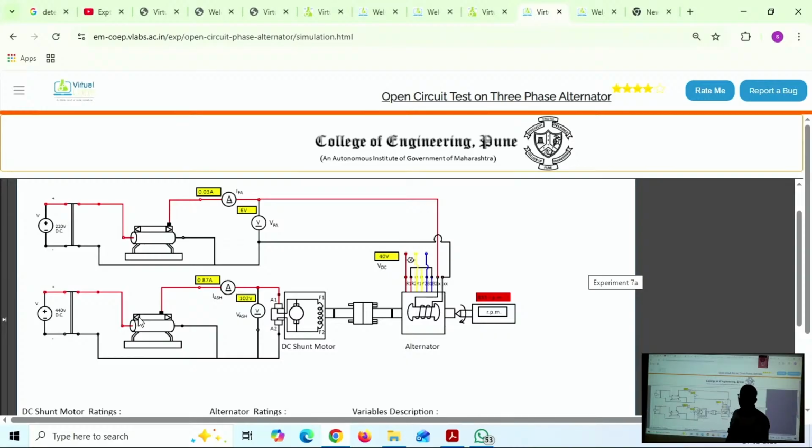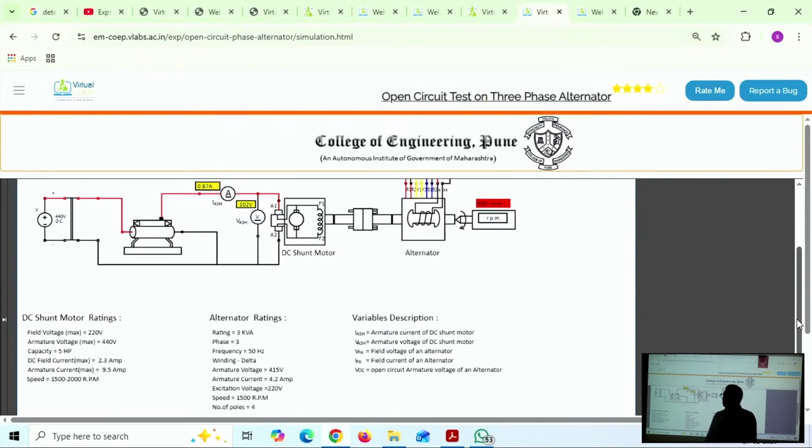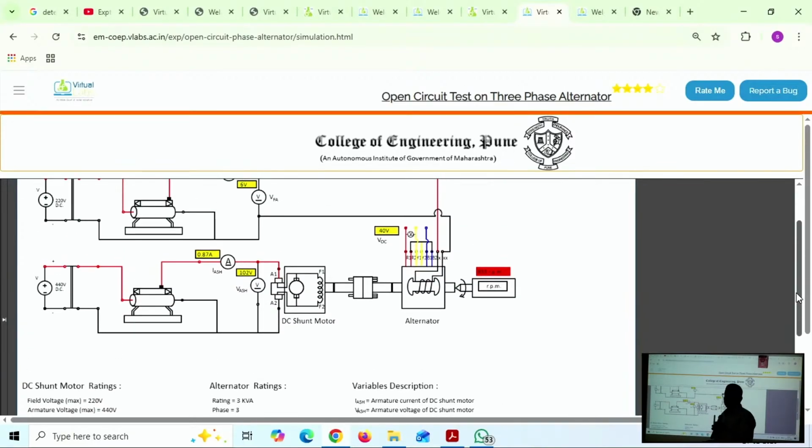So what should be employed? Speed control can happen in two ways: below the rated speed or above the rated speed. What control should we adopt here? If it is below the rated speed, what speed control method is useful? Armature voltage control. Okay. If we want speed above the rated speed, what method do we use? Flux control.